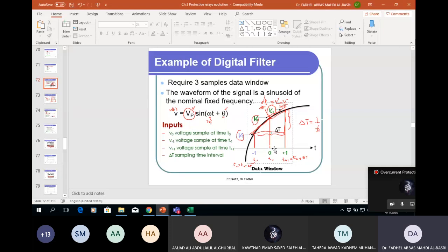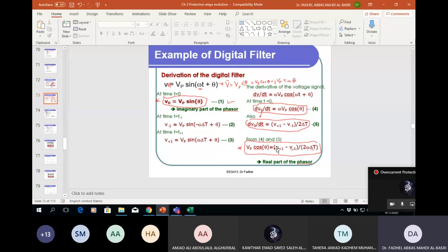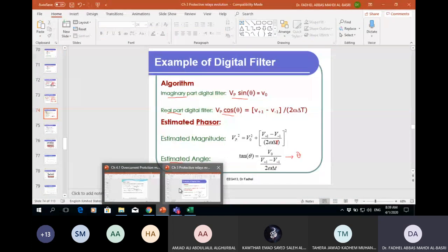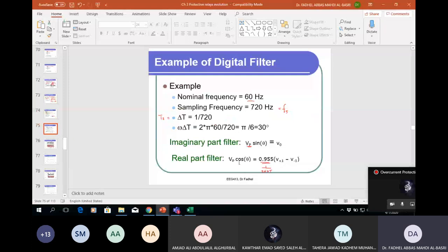You take a square root, you take the magnitude square of both signals. I have to estimate these two in a very fast way, right? If you have very short time, okay, that will limit, based on the microprocessor speed, your ability to take a higher sampling rate. Although a higher sampling rate is better, you have to look at your processing speed, DSP, microprocessor-based speed.